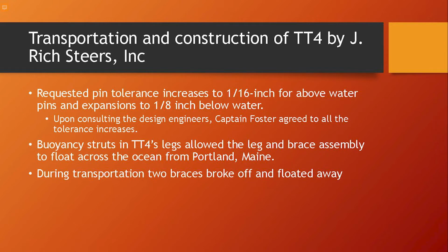While TT4 was being constructed on land, J. Rich Steers Inc. requested the Navy engineer to allow for pin tolerance increases. The design specified 1/64 inch tolerance, but they requested 1/16 inch for above water pins and 1/8 inch below water pins. Captain Foster, who oversaw the project from the Navy, approved all of these tolerance increases.